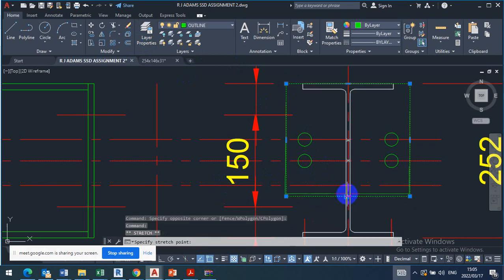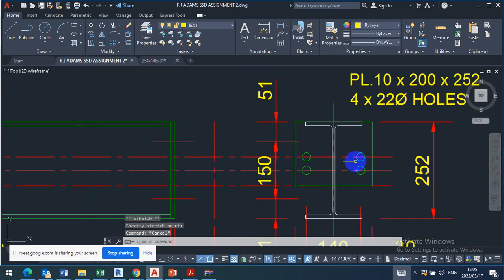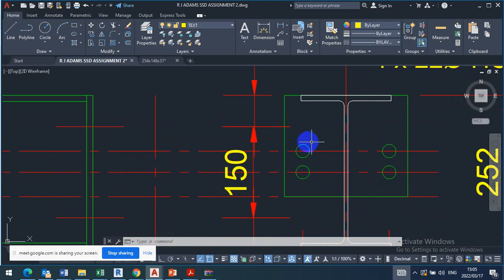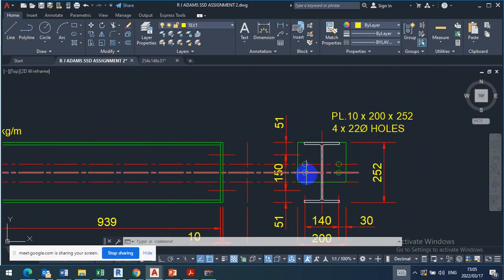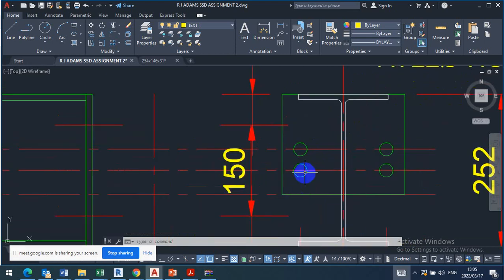40 or 50, because minimum is 40. You can cut it that way, but it looks very weird. Can you see they are too close to each other? That doesn't make sense. Oh, this is the center line. It's me who messed up. You should go down the center line, yeah. So let's say offset 3.5, enter.